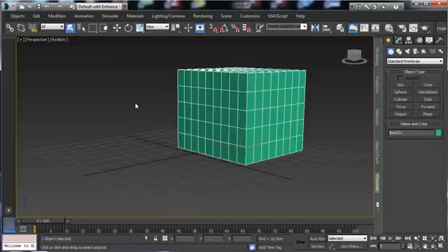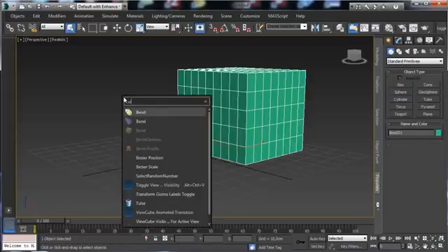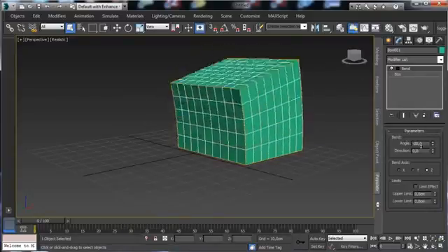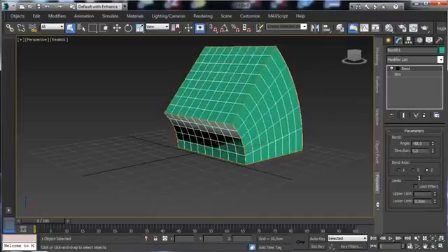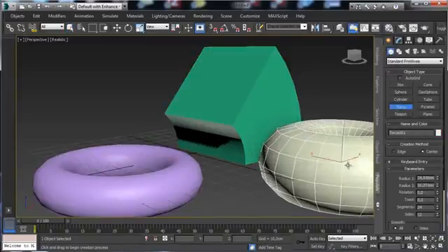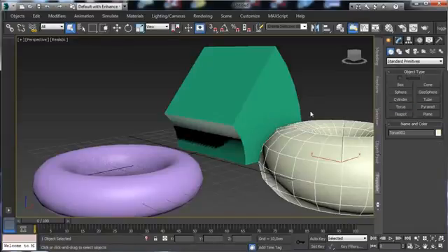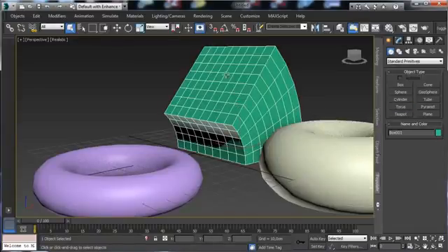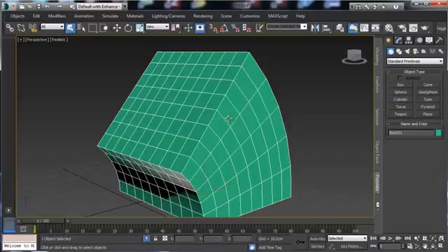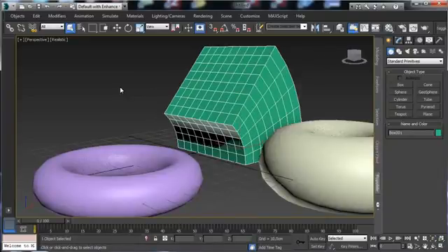Okay, we have done the modeling. If we like, for example, to use a bend modifier, we just have to say bend, and we have the bend modifier. So it is really faster to do something like that, because we have everything inside the viewport. Let's say that we have some more models and we'd like to do the isolation. It's really simple. The isolation is we select the objects and we click over isolate, but obviously now we can do the same there. We can write isolate selection, and that's all. So you see, it's a different way to work.